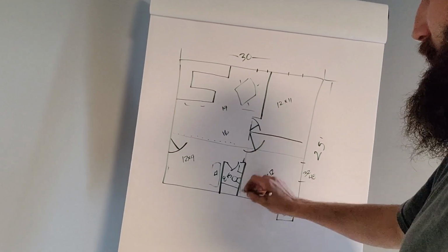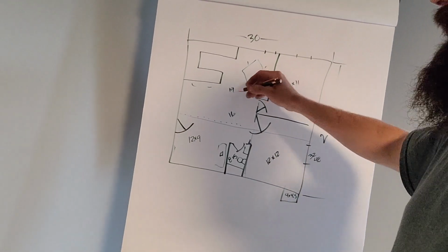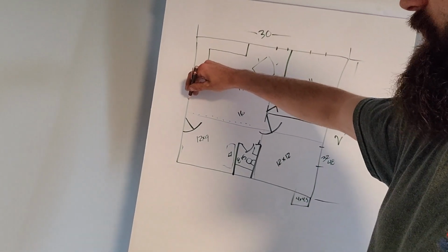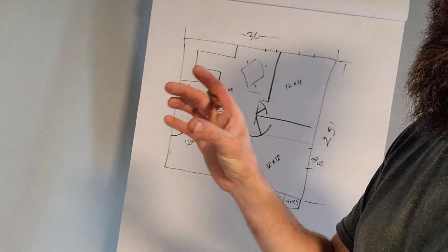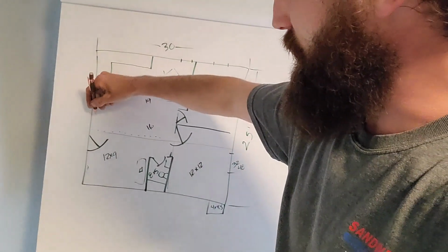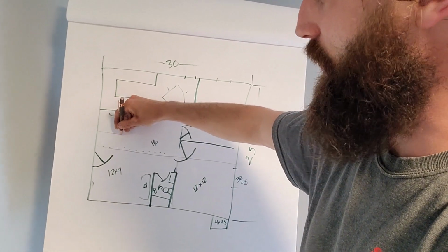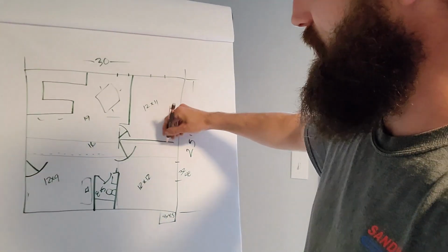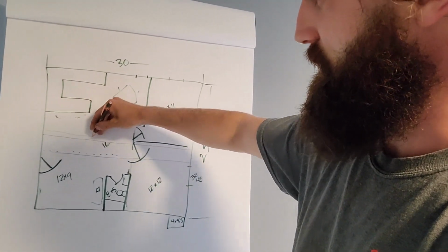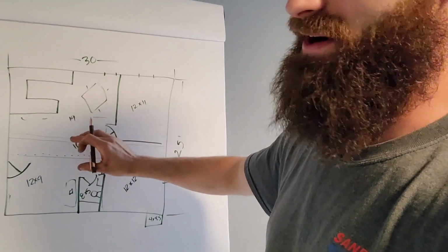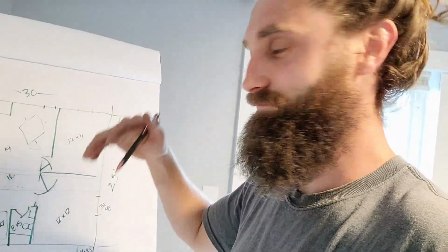Now, I do know here that, believe it or not, I don't know what the thought process was back in the 1800s, but these joists are spaced out on an 18 and then 20 inch and then 18 and then 20 inch spacing. The joists themselves are not a traditional 2x12, where it's 1.5 inch thick, 10 3/4 inches deep.